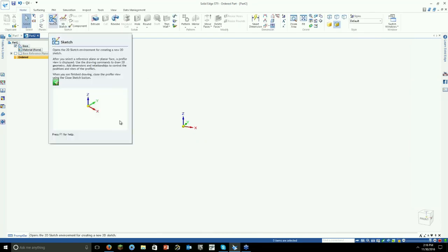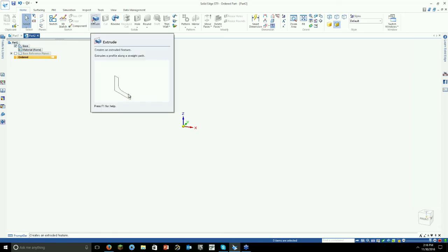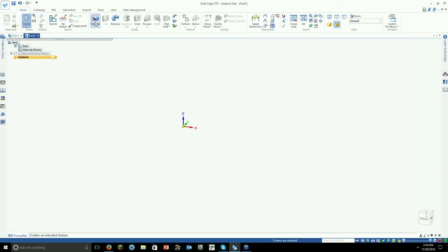So we have the option to create sketches, just like you create a region. The sketch would be its own feature in the Pathfinder, but the fact is you cannot delete it. If any features are based on it, everything subsequent after that would fail if that happens. So my workflow is to do my extrusions and revolves within the actual sketch profile within the geometry.